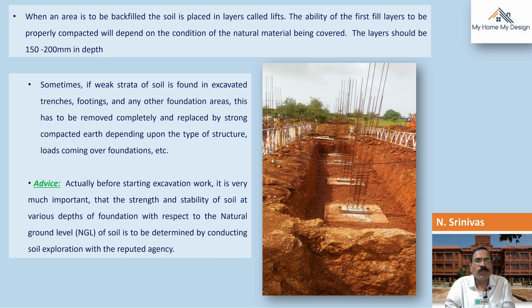Advice: before starting excavation work, it is very important that the strength and stability of the soil at various depths of foundation, with respect to the natural ground level NGL, is to be determined by conducting soil exploration with a reputed agency. You might ask a question: how can we know whether this soil is best suited for the backfilling or not, and what is the weak soil which is not suitable for backfilling purpose? Yes, of course. Before that, in order to determine what soil has to be used for the backfilling, better go for the soil exploration test.